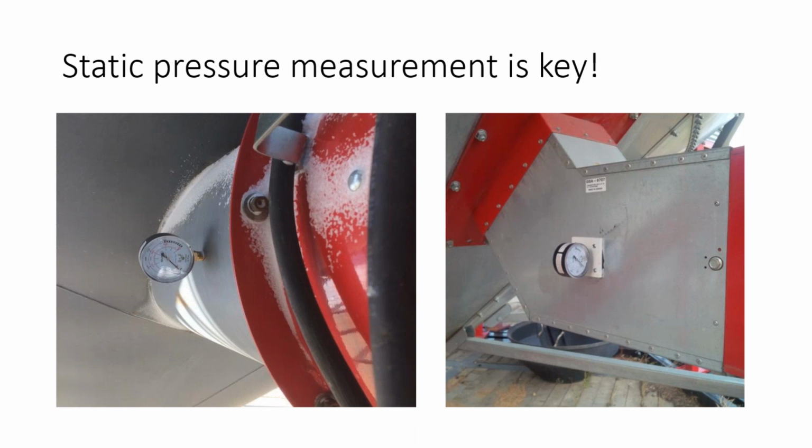The full floor aeration, you really can't do that test on. Manufacturers do not recommend running a full floor aeration bin without any grain in it, and you are risking doing damage. Ultimately, you really need to do comparative analysis with the different systems, and in order to do that, you need similar grain of similar moisture with the same fan operating on 2 bins with a different aeration system, and that really is the best way to understand the advantages.